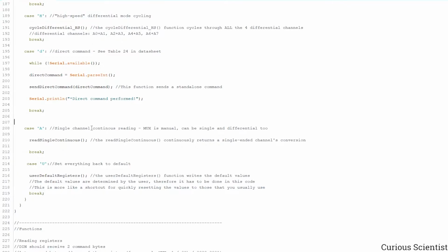So you select your channel by writing a register manually through this set of codes, and then you have to send this command. And when you send this command, the ADS1256 will get back to you with all the data captured from one single input.